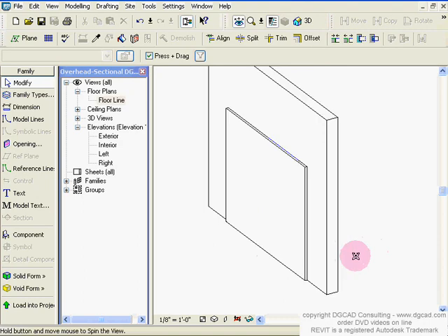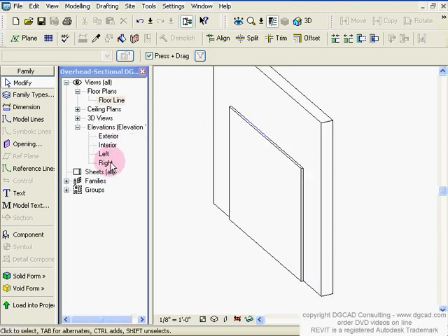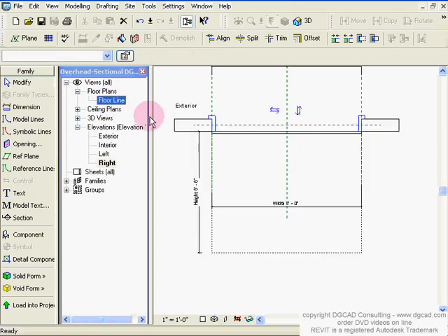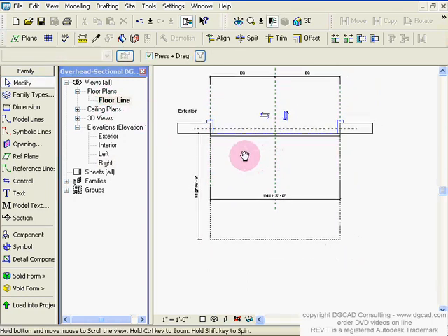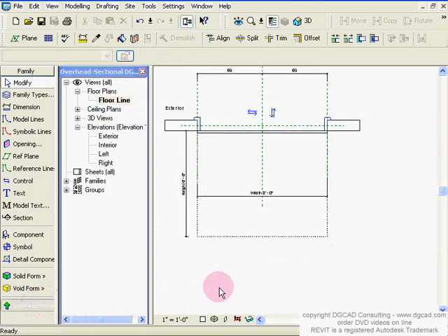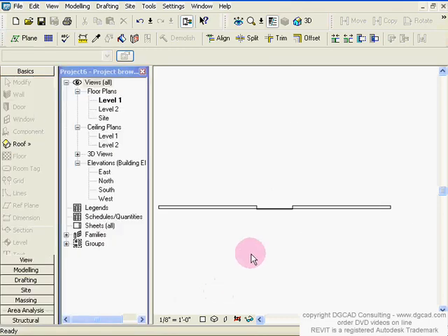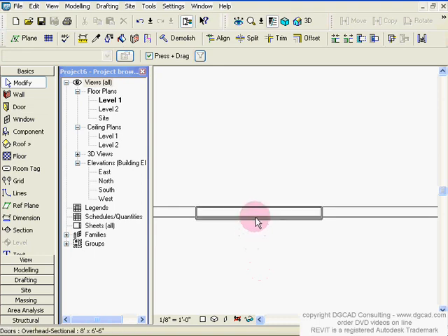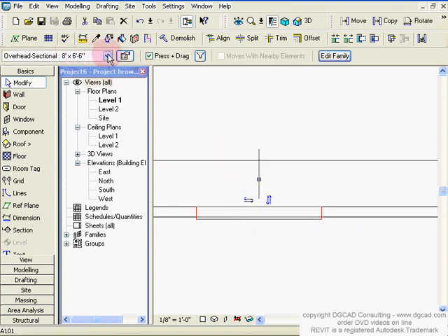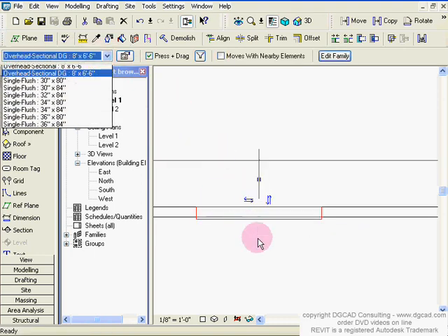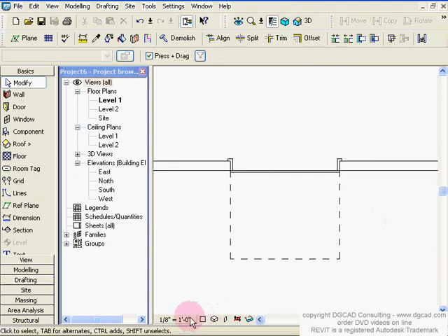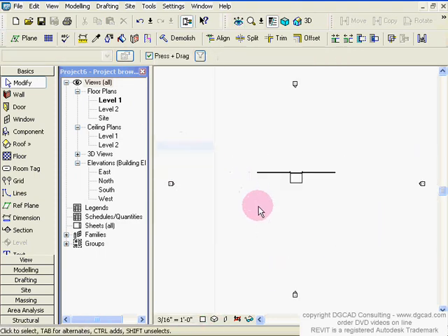Okay, and now this one in 3D, of course, you won't see those model lines. Okay, in the right side, you don't see those lines. Only when you look from here, you will see those lines. So let's try pushing that out to a project. Let's go over to here, load to project, and then I'm just going to add one in, click on it, click out. Now, is that mine? It's not mine. I want the DG one. DG one, look at that, comes with dashed lines.